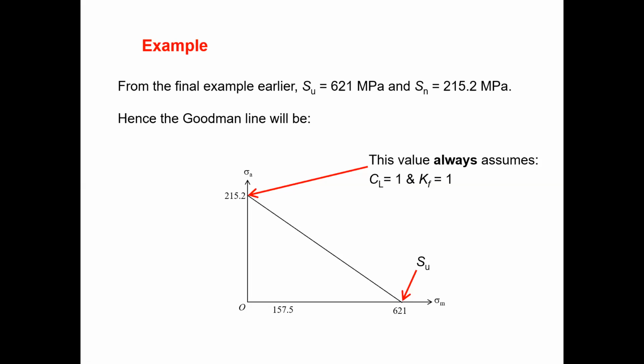If you remember when you did the calculation last time in the tutorial, at the loading point there is no stress raiser. So that means Kf equals 1. Normally if a stress raiser is introduced, the Kf value will be greater than 1. That is what normally will happen, isn't it? If you remember. So normally in this kind of question we are not going to introduce Kf into the strength. We will introduce the Kf for the stress.